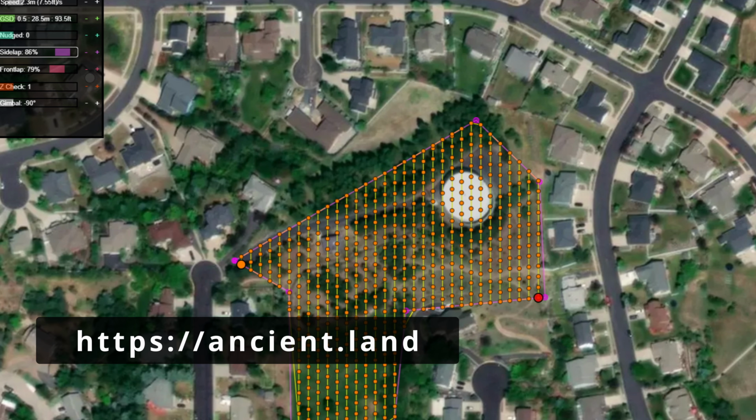There is a free tool where you can set up the survey mission. It'll map it all out for you, figure out the camera trigger points, and plan the waypoints for you. You can then export that as a CSV, load that CSV into Lychee, and then Lychee will go run that mission for you. So much cheaper, $25 one-time purchase, a little bit more work.